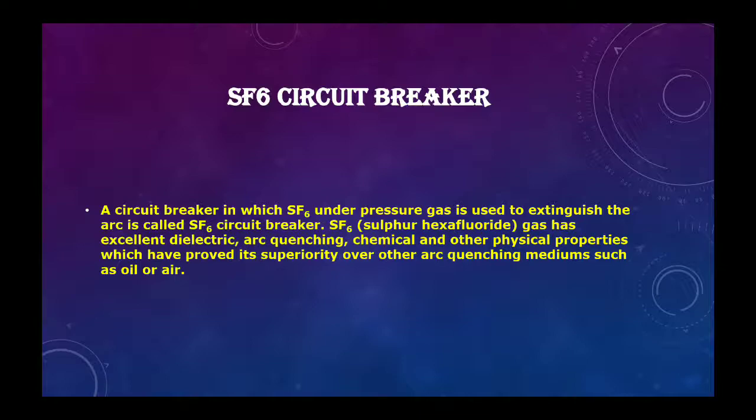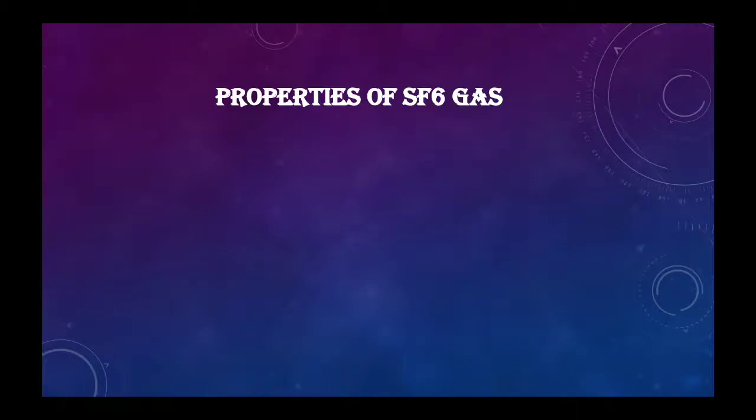It has excellent dielectric and arc quenching properties, and chemical and other physical properties which have proved its superiority over other arc quenching media such as oil or air. Now the properties of SF6 gas. There are different types of dielectric and arc quenching properties present in SF6 gas.